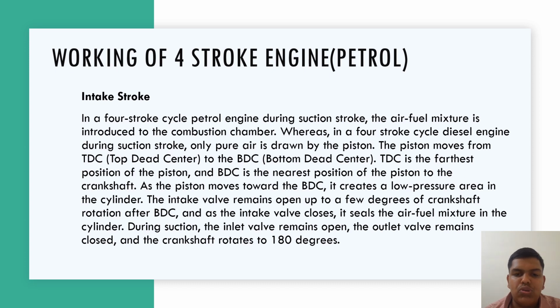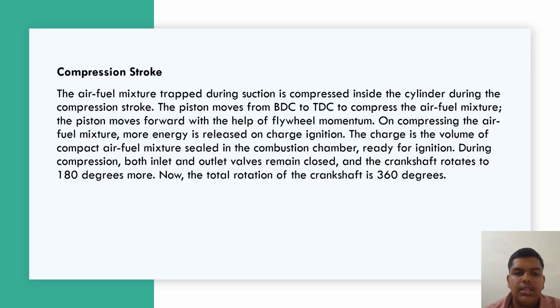As the piston moves towards the BDC, it creates a low pressure area in the cylinder. The intake valve remains open for a few degrees of crankshaft rotation after BDC, and as the intake valve closes, it seals the air-fuel mixture in the cylinder during suction. The inlet valve remains open, the outlet valve remains closed, and the crankshaft rotates 180 degrees.